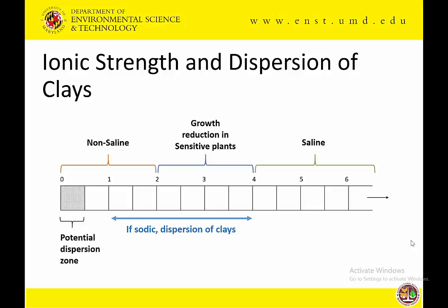What people in Georgia found starting in about the late 80s when they were studying erosion and crusting and all, was that in regions of high rainfall, and they get 50 inches of rain a year, pretty much like us, evenly distributed across the months, is that they were observing dispersion with low electrical conductivity soils, something which is still not widely recognized among many people in the profession unless they were interested in reading this literature. So we can get dispersion here too, all right? There's plenty of evidence to show that.